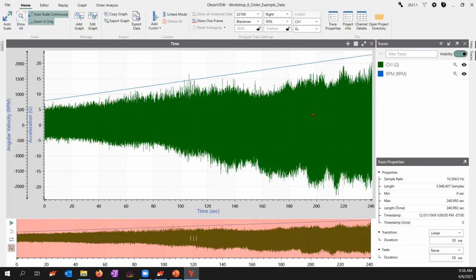So there was a customer out there that had a problem with a sensor on an engine. And as I mentioned before, they were seeing field failures, but they weren't seeing failures in their lab. And the reason is because products mounted on an engine, as you can imagine, as the engine moves because of its RPM, it creates a very strong sinusoidal waveform that follows the RPM of the engine.